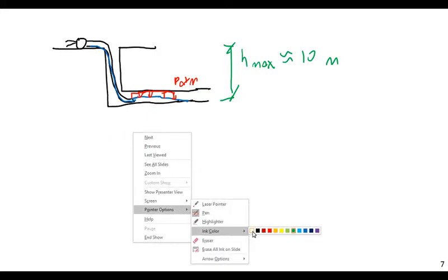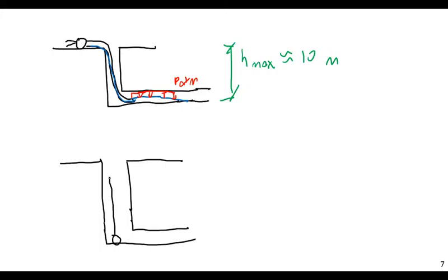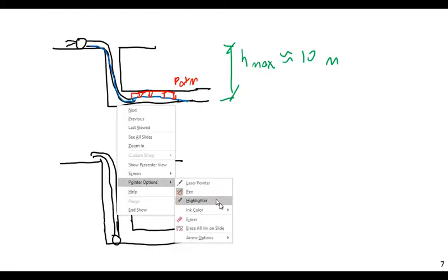So what they do instead is arrange it so the pump is at the bottom of the mine. You'll probably use a submersible pump or something like that, either right in that pond at the bottom, or adjacent to it. And the pump is not limited to atmospheric pressure. It can pump up to the limits of design and materials. So it can pressurize this thing to 10 atmospheres, or 100 atmospheres, or whatever is required to pump the water out of the mine.